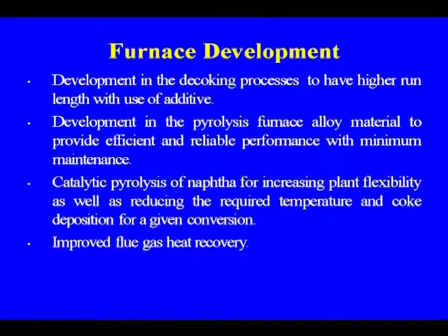So, in case of the furnace, some of the other developments, especially from the coke formation point of view and the corrosion point of view, has been the development in the decoking process to have higher run length with use of additives, development in the pyrolysis furnace alloy material to provide efficient and reliable performance with minimum maintenance. Because you see, that is one of the problems in case of the refinery and the petrochemical complex also, because you are using a large number of furnaces, and so the corrosion problem is severe if the feed is not properly treated or the removal of the sour gases is not there properly.